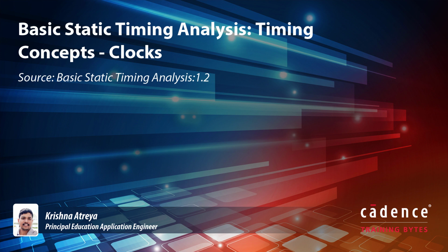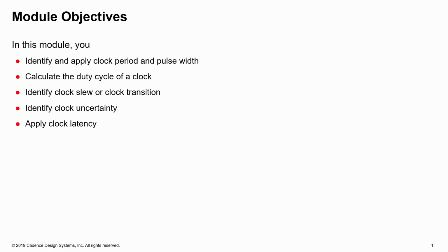In this module, let's look at clocks. Let's identify what a clock is, how a clock is defined, what the clock period, pulse width, duty cycle, and all the different properties of a clock are. And we'll also look at how a clock is actually propagated in a design.